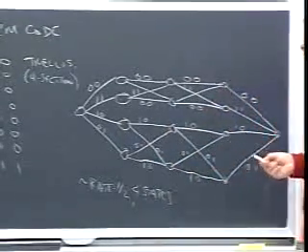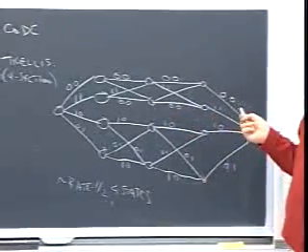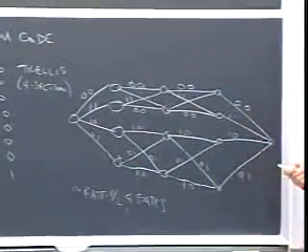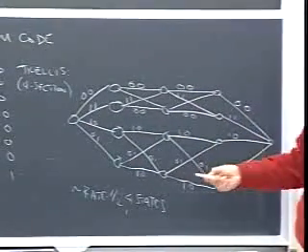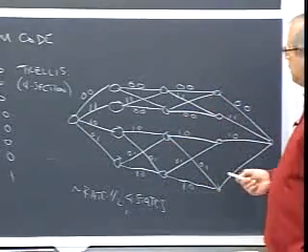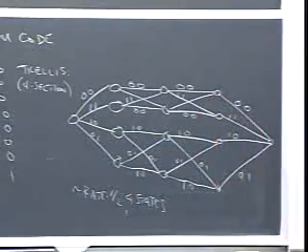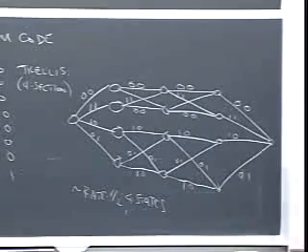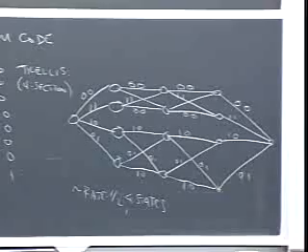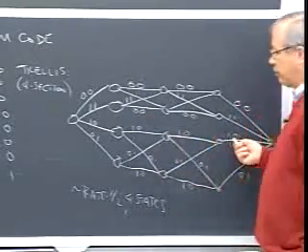Of course, it's not time invariant. It doesn't go on forever like for a convolutional code. A block code only exists over a finite time. So we're going to get a block trellis that starts at a particular time and ends at a particular time in a single state. But we want the basic property that the paths in this trellis are in one-to-one correspondence with the words in the code. So how many words are there in the code? There are 16 in this code. How many paths are there through this trellis?